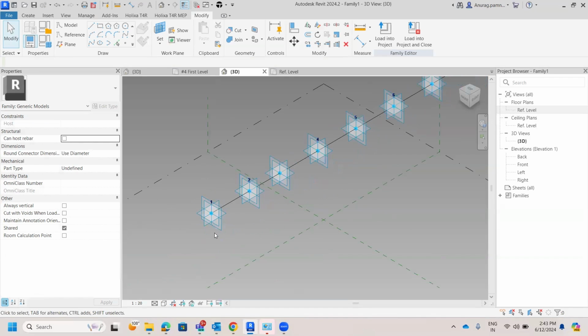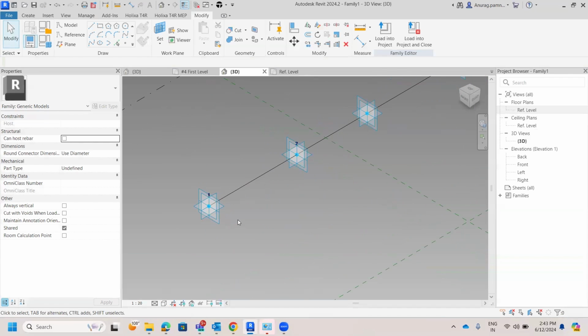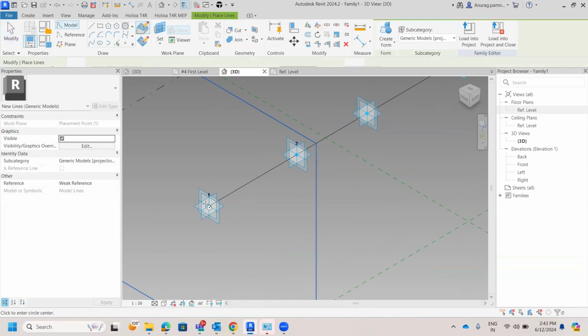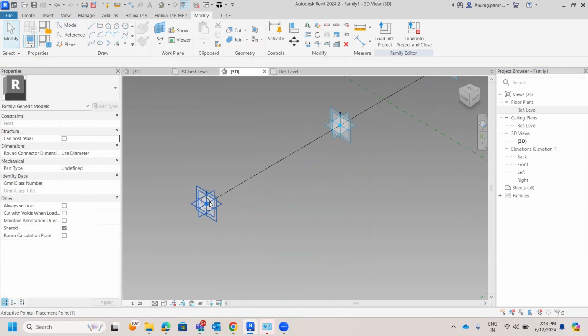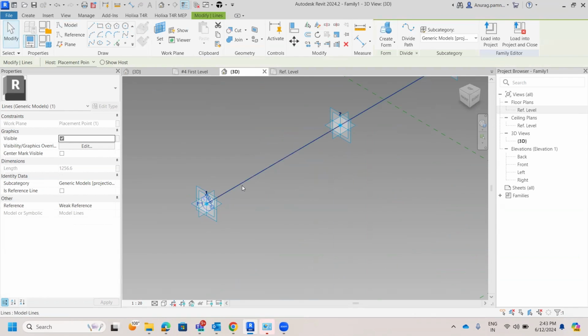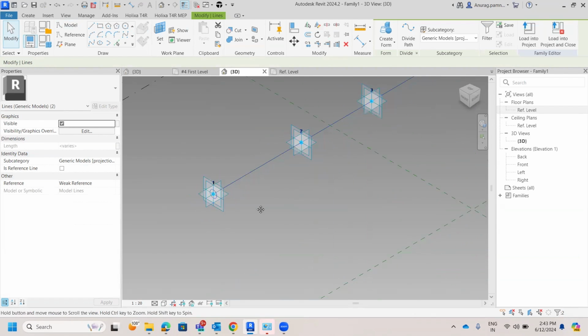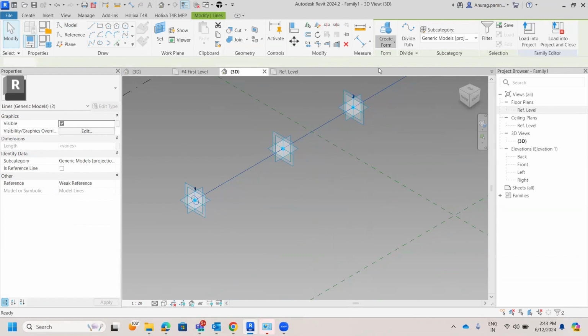So now we are going to develop a surface. Let's develop a pipe sort of structure. So first of all, let's just select the work plane in which I have to work. So right now I have this vertical plane to work with. I'm taking a bit smaller surface, right? I will just select the surface. I will select the path so it works the same as a sweep model and we are going to create a solid form out of it.